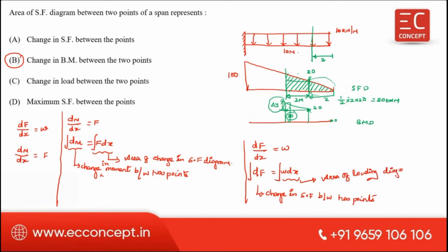In the same example, if you want to find the change in shear force at this point, then you have to take the area of this loading diagram. This is the rectangle, right? 10 into 2, you will get 20. That's a simple concept.